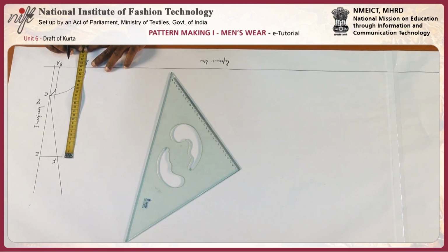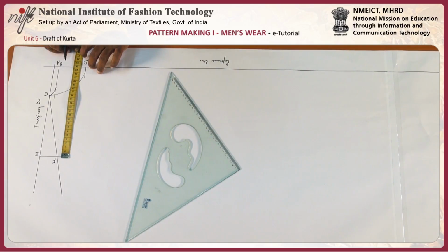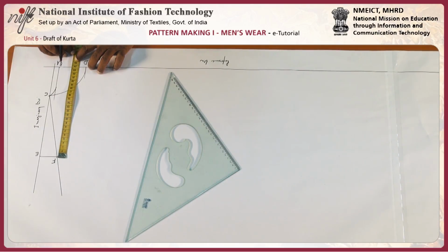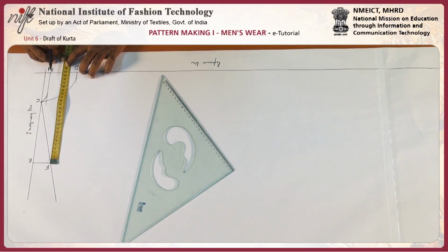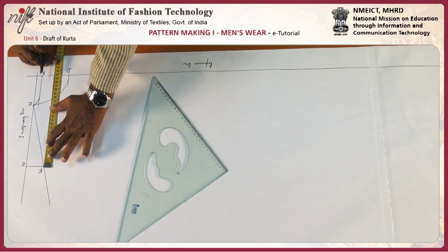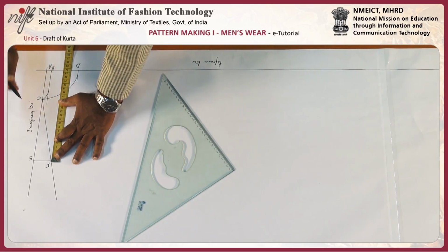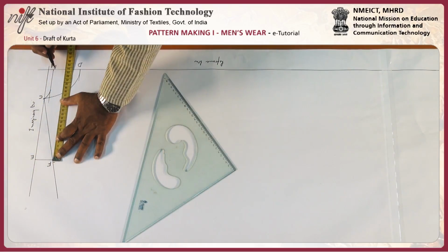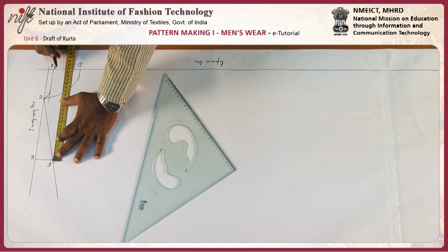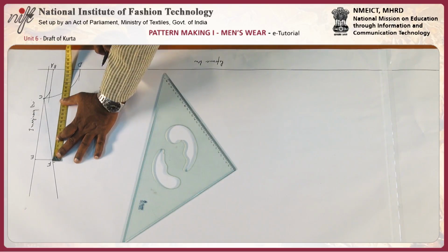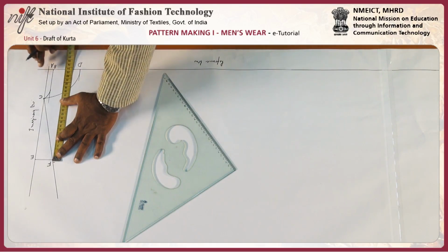You can very closely watch what I am doing to get point G and H, which is half across shoulder, 23 point, full will be 47. See, it is intersecting here, so this point will be H and this point will be G. So G and H you need to derive by placing 23.5 on the reference line and taking the intersection.